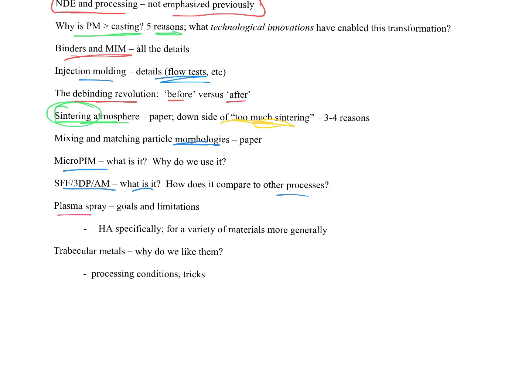All right, and then plasma spraying. We know what the goal of plasma spraying is. We know what the ideal picture of plasma spraying is, but now, based on what I showed you in those videos and so forth, you should have some clear idea of the limitations of plasma spraying, and that it's not an isothermal type of process. It's a gradually adding some here and there sort of process. It's not like we form it all at once. And so because of that limitation, there are limitations in terms of the goodness of the coatings that we make. And we overcome that because we're not asking those coatings to have fantastic properties. What they sit on has to have fantastic properties, and the process of coating it shouldn't compromise those properties.